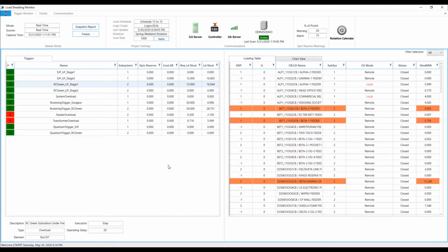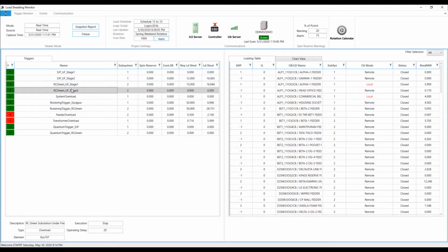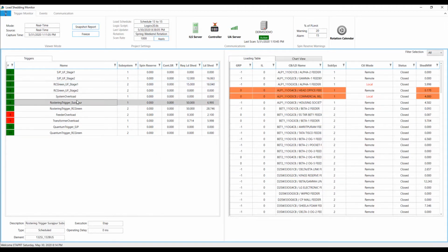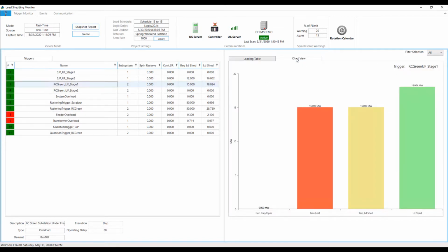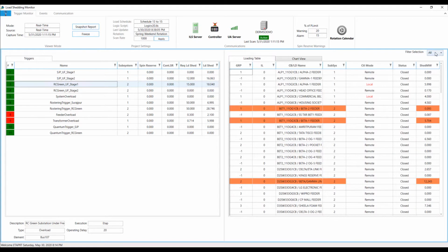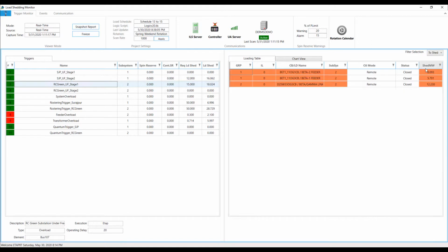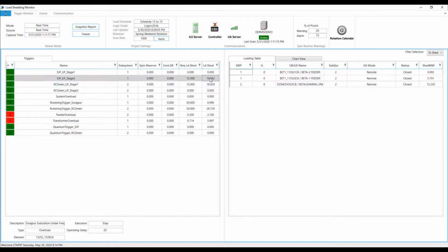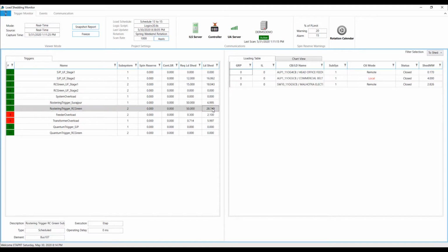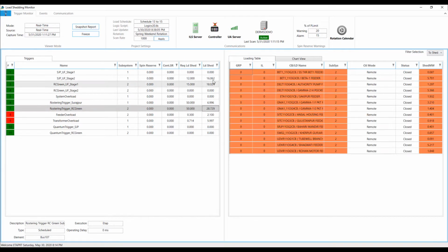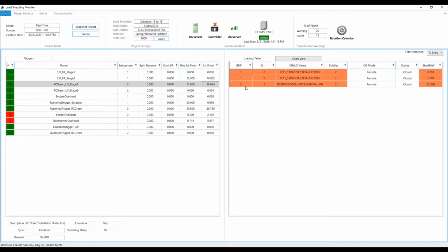The load sharing data is monitored from an easy-to-use and operate load sharing monitor application, which displays the list of triggers and loads that will be shed if any of the conditions were to become true. The what-if analysis is done continuously by the ETAP Intelligent Distribution Load Sharing Engine, and the results are displayed on the monitor as well as armed to all the controllers on the field. The monitor displays the amount of load that is selected to be shed for every scenario, as well as a list of loads to be shed based on the user-defined priorities.